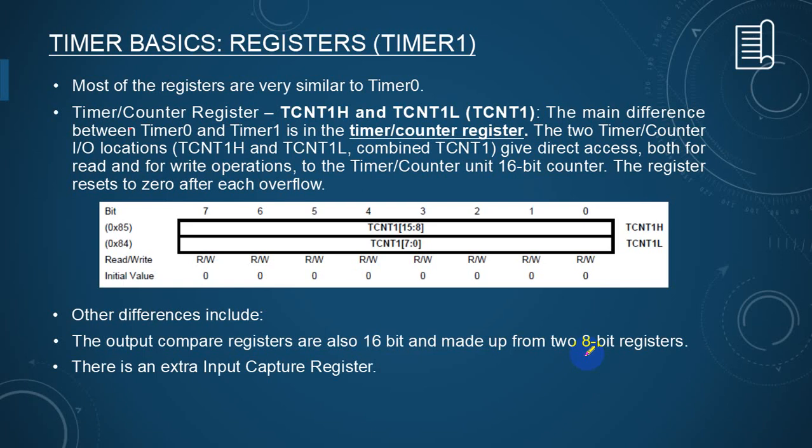We have seen two modes: the normal mode of operation, sometimes called overflow, and another mode, clear the timer on compare. Another mode you can create: when you get an interrupt or a special signal from outside, from the CPU for other operation, then you read the count, just like a stopwatch.